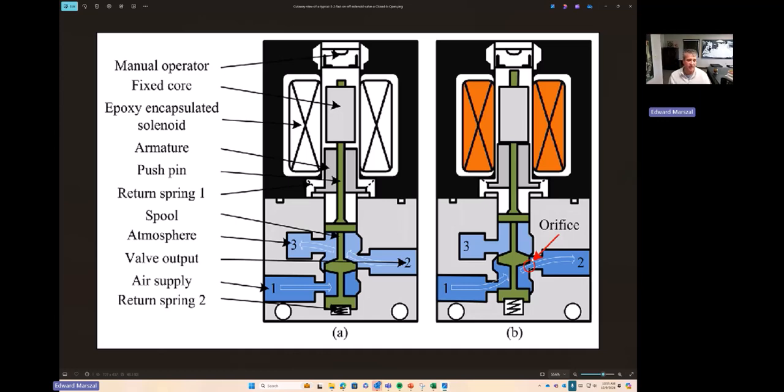There's a joke I heard in the past: hey, somebody put some air in my instrument water. Because if your instrument air conditioning is not good, you might fill up your instrument air system with water instead of air. And I'm aware of one accident in history where all of their final elements failed at the same time, common cause. How did this happen?